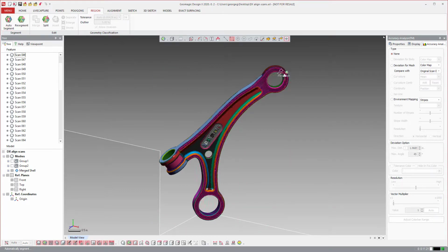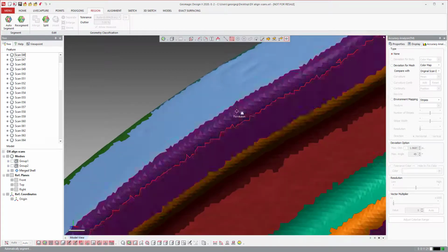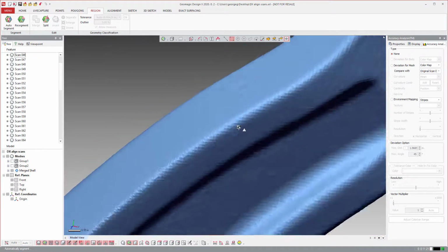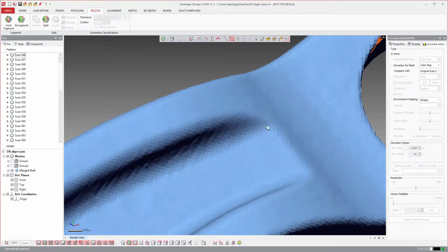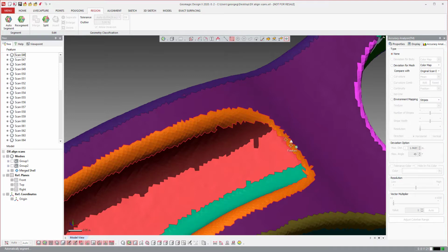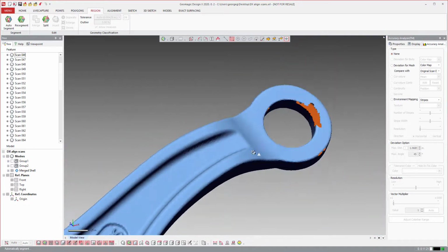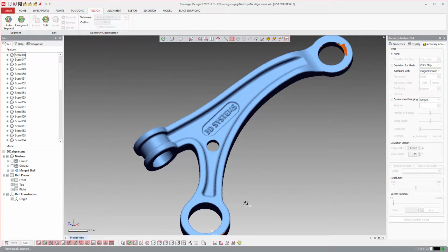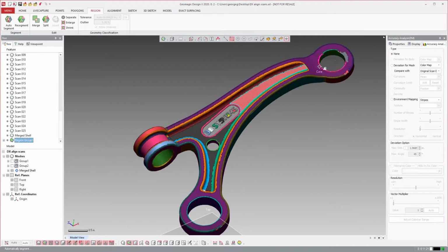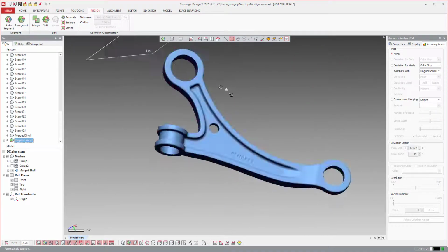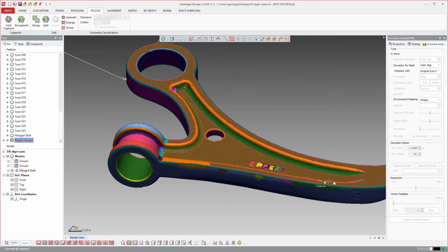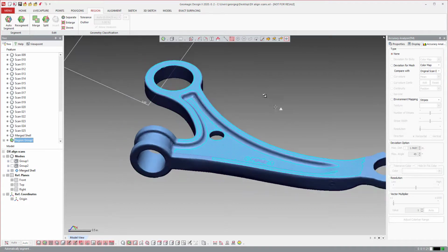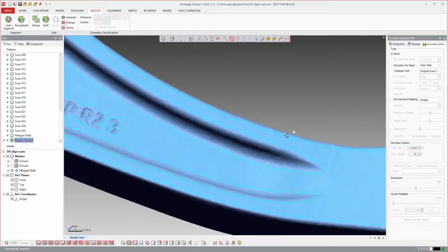But if they are not perfectly flat, which this shape is described by triangles, they have different common angles between them. So this auto segment region group, what it's going to do is group triangles by common curvature or angles between those triangles. And what it inherently does, as you can see, is makes it really easy to select regions of the part. Again, why we call it the region grouping tool or regions. It makes it really easy to just grab that whole face and use it to best fit a plane or whatever. So these are like a giant saved selection is one way that I put it too.